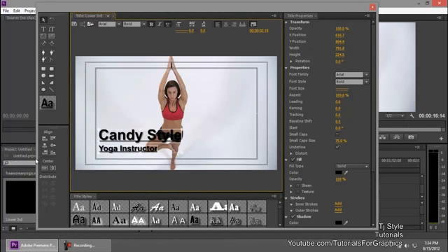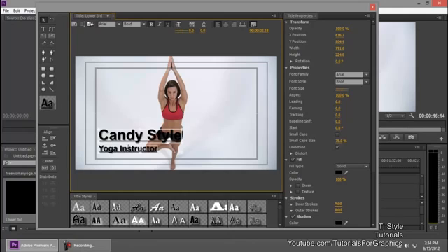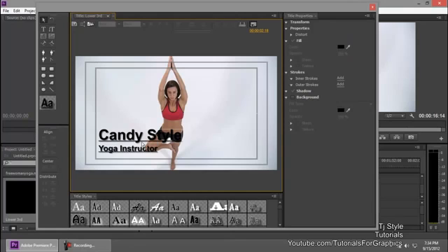Okay, so we have aligned our text together. If you haven't seen that, or if I forgot to show you how to do that, first select these two texts together, then go to this Align tab and hit Horizontal Left. Of course you can eyeball the text if you want to, but for professionalism and proper accuracy, just select both of them, Align, Horizontal Left, and they'll be all aligned over there.